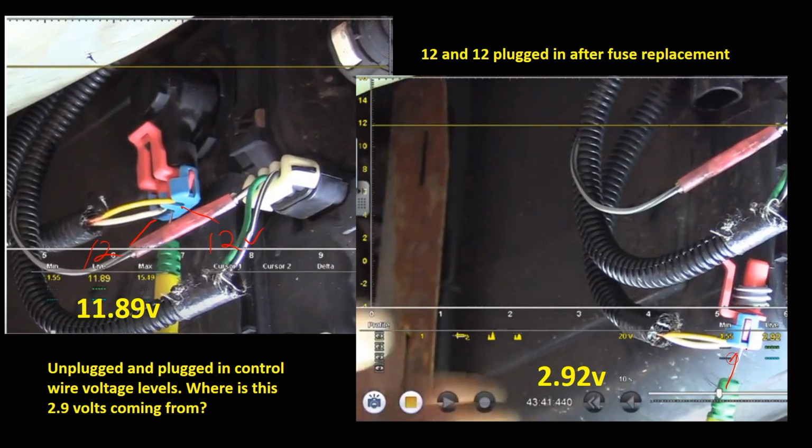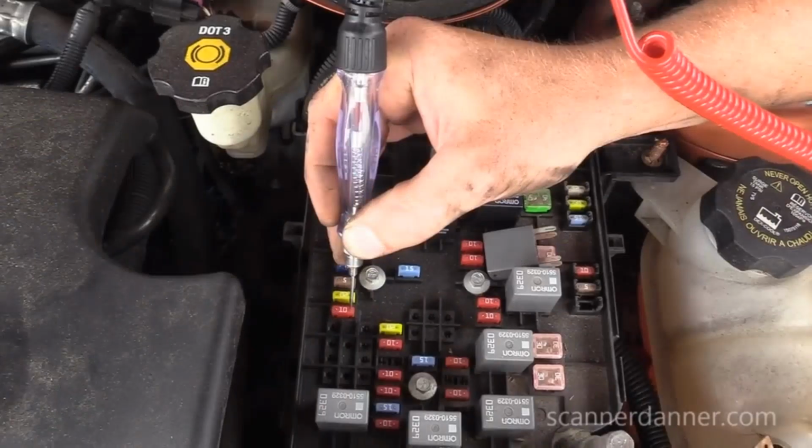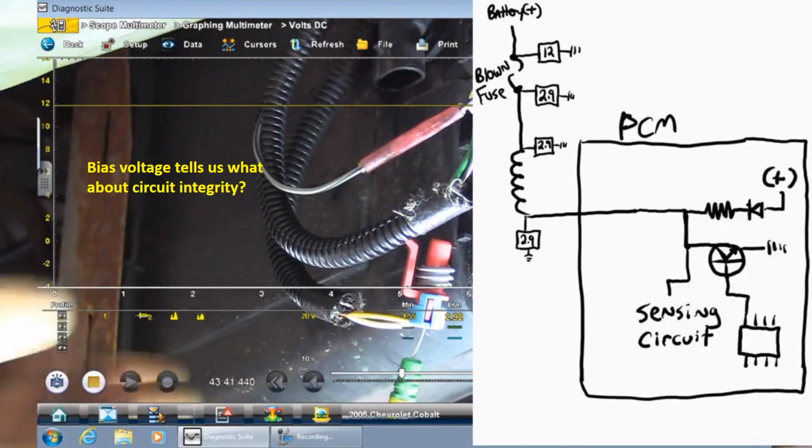I did the same measurement on the two wires, and I'm reading 2.92 volts with it unplugged. So you can't kind of see that here. This is plugged in, and this is unplugged, 2.92. And I'm sorry, unplugged, I only saw that on one wire. Caleb, I need to add some extra slides here, because I needed to emphasize that this picture is just the control wire that I'm on now. Here's the explanation right here. I'm on the control wire for this component, okay?